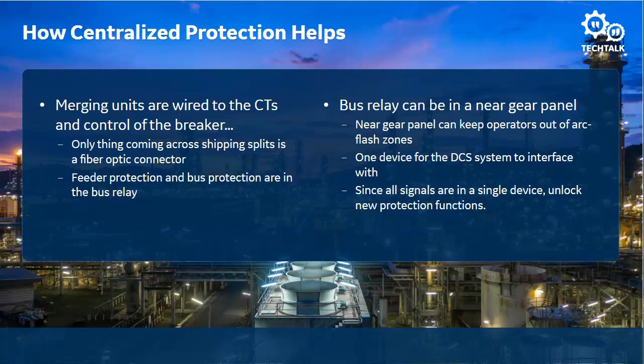What I mean by new protection schemes is it makes it very easy and very simple to use zone selective interlocking schemes between the feeders. It makes it very easy to do other protection schemes that would have been more complicated to share across multiple discrete relays.